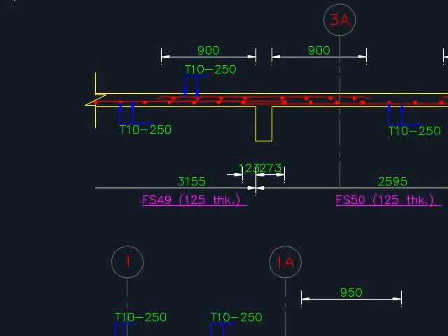Of course, if you don't want to fully abide by Lx must be the main reinforcement bar, you can actually apply every slab to be in the same arrangement of the main reinforcement bar and the secondary reinforcement bar. That means regardless of Lx and Ly, both planes will have the same set of arrangement.